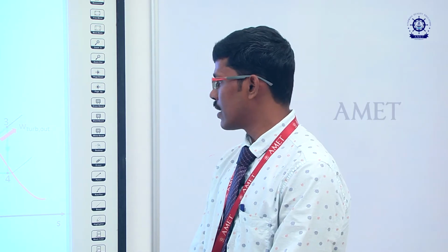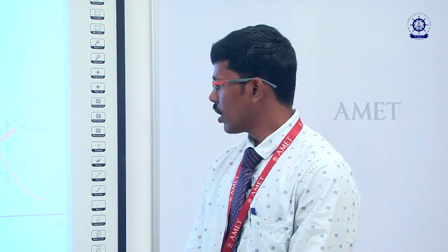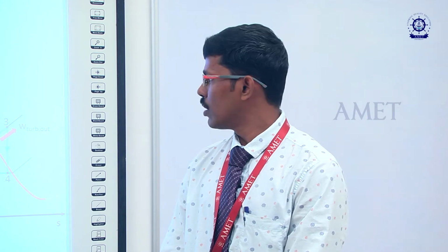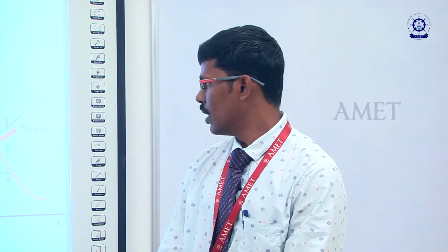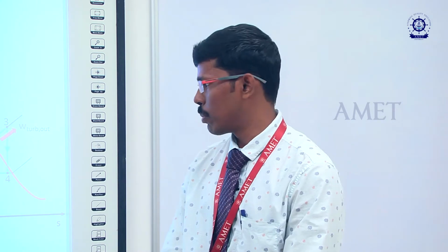Here in the TS diagram we have a saturated dome. Basically it gives the average values of saturated states at different pressures. To the left of the dome, from the top, it shows the saturated liquid region, and from the top to the middle of the saturated dome, on the right hand side, it shows the saturated vapor curve. So this curve gives a clear idea about where the saturated liquid and the saturated vapor stand.